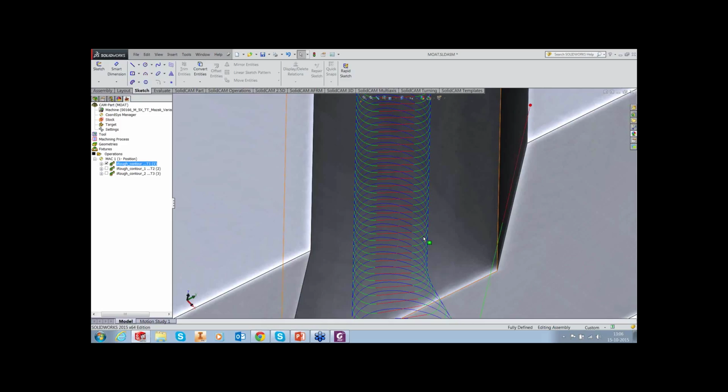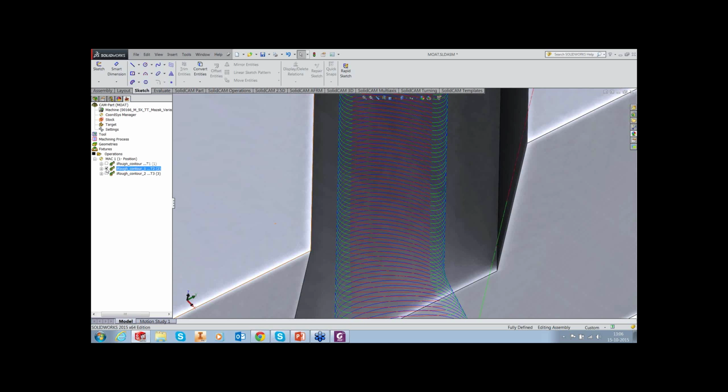There must be a nice cutting, it should leave nicely, and it should come back and re-engage itself nicely into the material. Now, the same area, when machined with a 12 diameter tool, I get much more width for cutting. So it has got much more area to cut, leave that cut, go nicely and re-enter it.